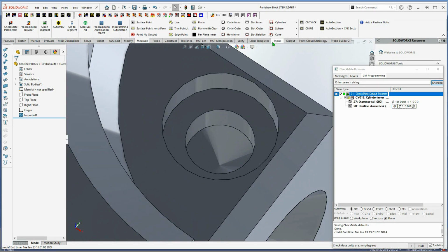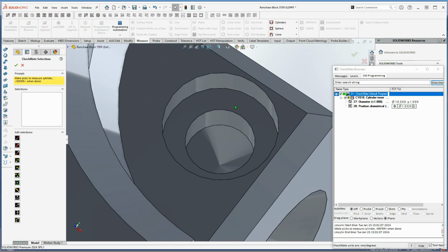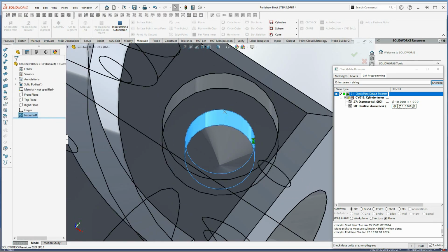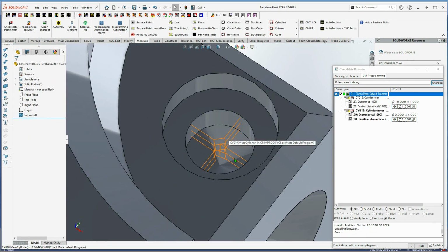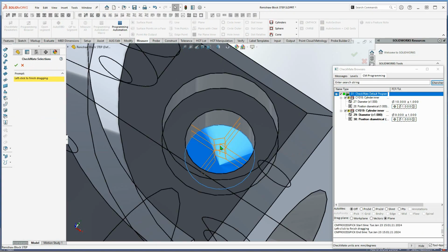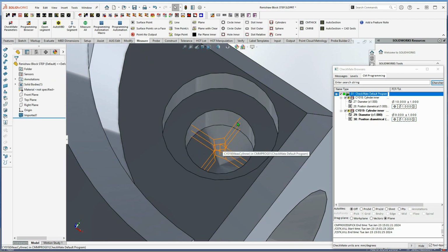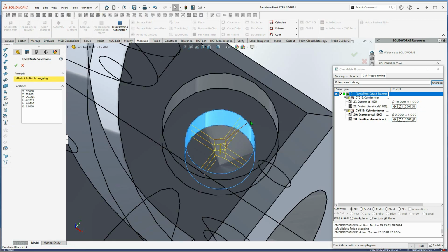and I were to measure a cylinder, then I now see 12 points on 3 levels. And the ability to drag these around is preserved. If I hit Shift and pick the normal, then I can move that up and down. If I hit Shift, this is the left shift, and pick one of these, I can move that anywhere I want. It's constrained to an arc.